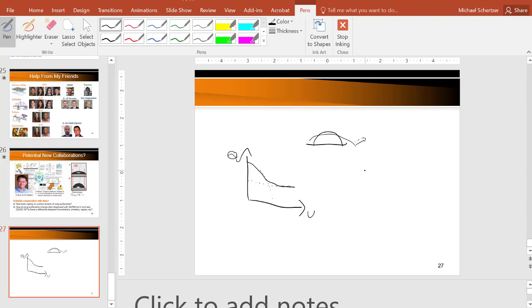Mike, I have one question. When I work on soft material cutting, in the very beginning, we need to break the surface, using a blade to break the surface. So we really care about surface energy, or how much energy we need to break the surface. I'm wondering, what is the best way to measure the surface energy? We try to use a contact angle to estimate surface energy, but the estimate is much lower than the actual surface energy.